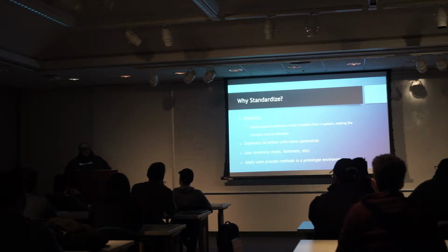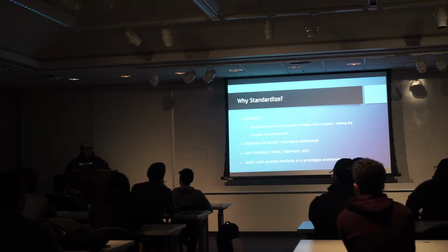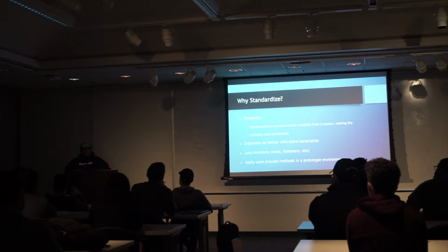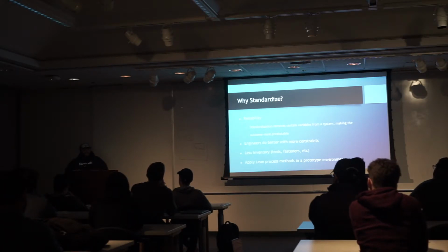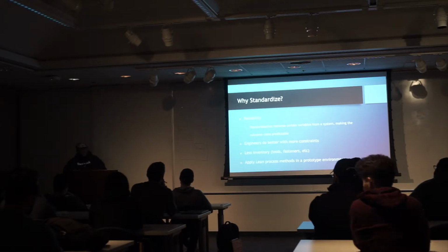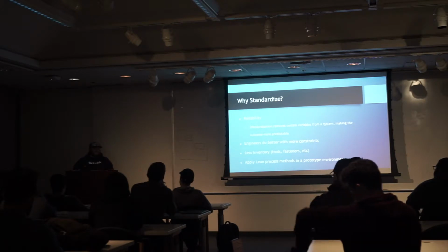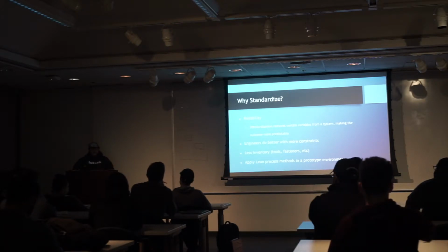Obviously, if you standardize, you have less inventory. You're not buying weird tools or specialty tools for everything under the sun, because one person wants to use M3 bolts, the other person wants to use 4-40, and whatever. If you put some standardization into it, then you can just take half the car apart with a 3/16 Allen wrench. And the same goes for bearings and end mills, drills, taps. So in the long run, you save money because you're not buying all these specialty tools or really long end mills or drills.